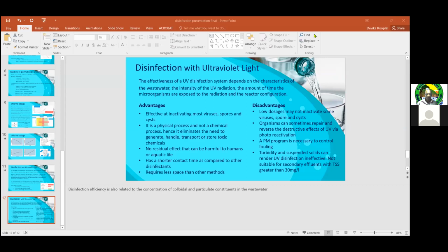So you'll take longer to overcome that chlorine demand. You'll find that you're dosing chlorine, but you're not seeing a residual. You're measuring residual chlorine, but you're still getting zero, because something is there that is generating this turbidity, but it's also reacting with your chlorine.